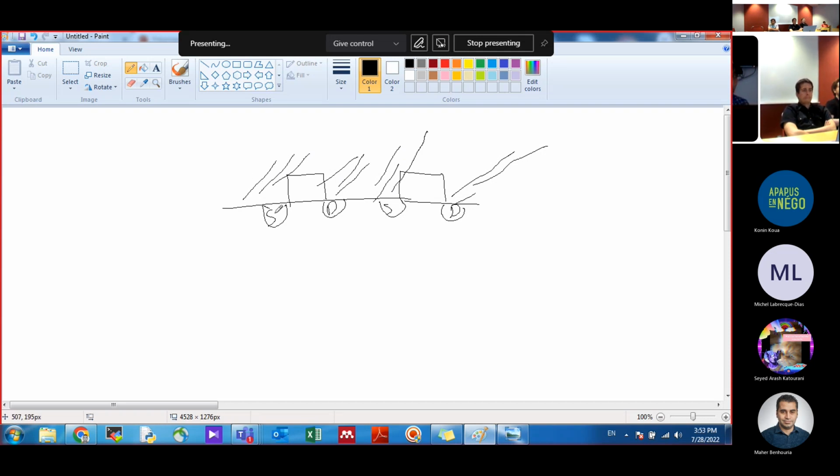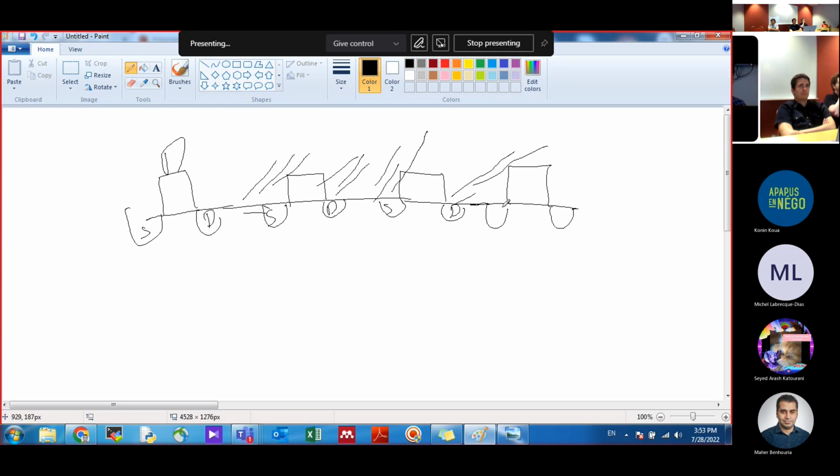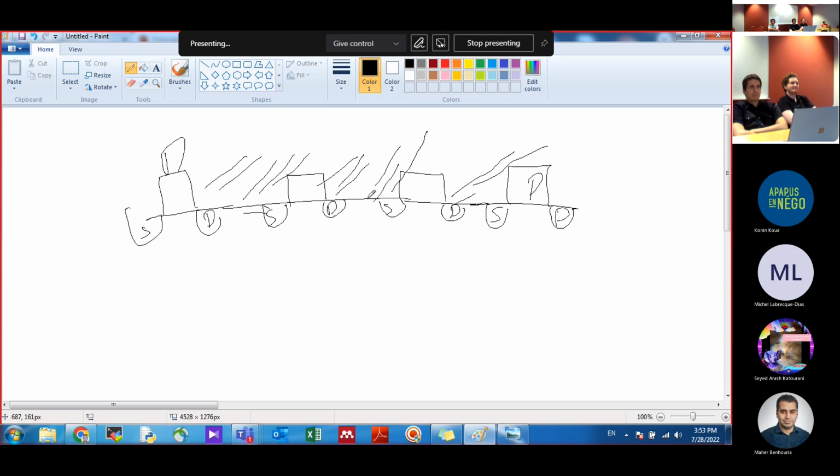So you add dummies to compensate for that. Dummies will be like source and drain dummies, at the same distance, everything. So we will have bad implantation everywhere. Of course. So this one also, the source will see the same thing that this one sees, bad implantation, and this one is also a good one.